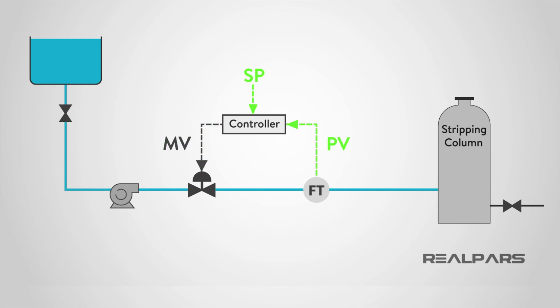To answer that question, I will need to understand how the process responds to a change in the error. The algorithm I choose will be a function of the error. When the error is small, I will make a small correction. When the error is large, a larger correction is required. But how big should these corrections be?